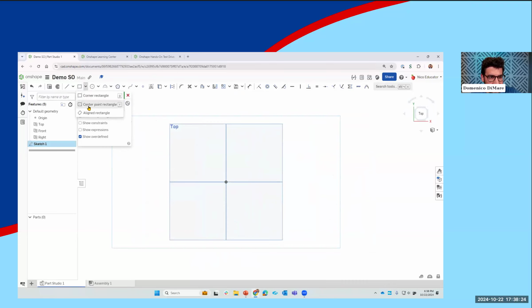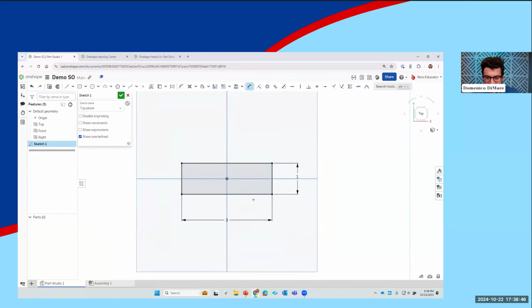So I'm going to make a pulley bracket here. Pretty easy. I'm going to start with a rectangle. I can use a dimension tool here to add the actual dimensions of what this is going to be. So maybe we'll make it 3 by 1 inches. That's going to be the bottom of the bracket.